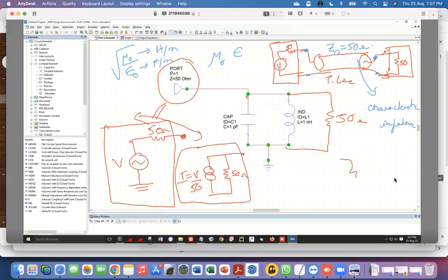And this determines how the voltage and current at any point along the transmission line will be. It's this number which has to be 50 ohms in order for there to be no reflection at these points. So here again, there's a combination of lumped element description and wave description. You can always have points which are spatially localized, and you can define currents and voltages at those points.